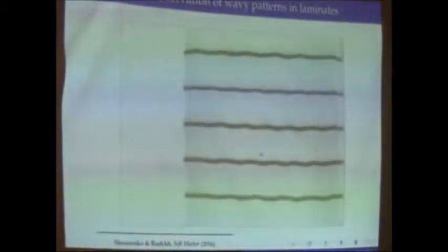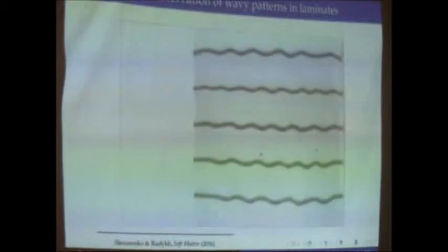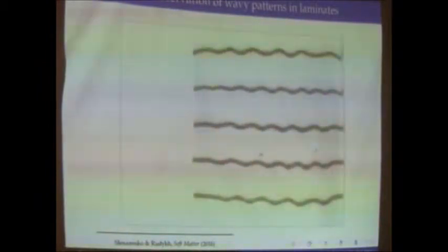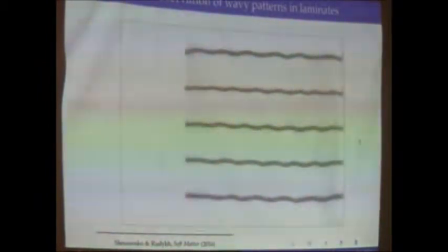I can see these wavy patterns form, and I like it very much because it really agrees very well with analytical predictions, the wavelengths and the critical strain, etc. So for the analysis that we very briefly do here, again, we use Bloch-Floquet analysis, and we scan over any k to find the right wavelengths for these instabilities, right?